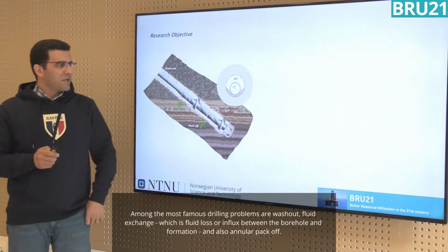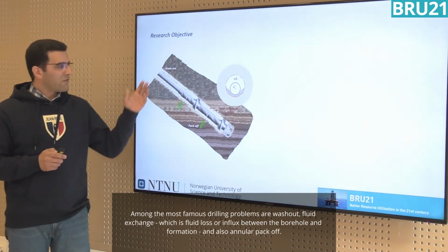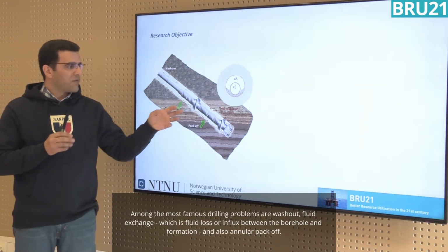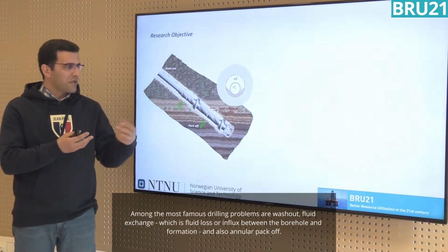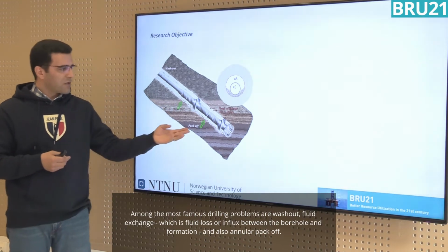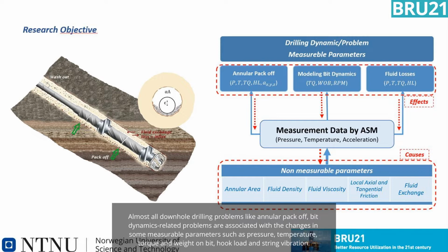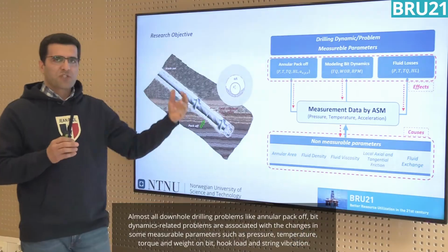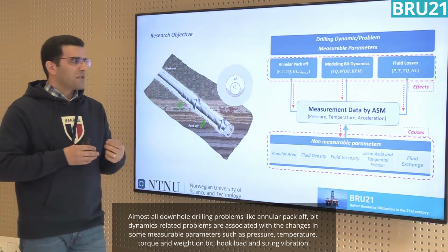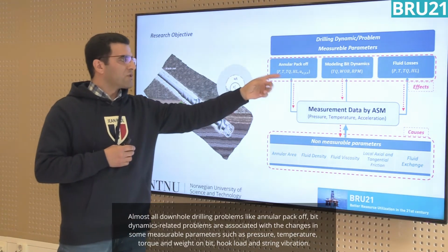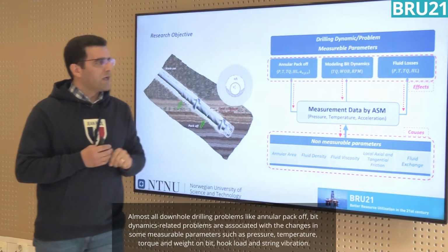Among the most famous drilling problems are washout, fluid exchange, which is fluid loss or influxes between the borehole and the formation, and also pack-off. Almost all downhole drilling problems like annular pack-off, bit dynamics, and fluid losses are associated with the change in some measurable parameters such as pressure, temperature, torque, hook load, and vibrations.